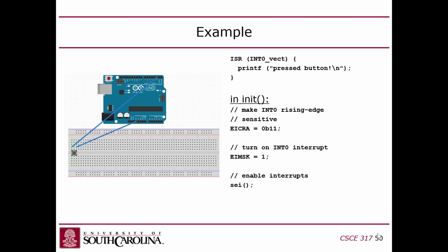All right. I don't show what I have after this, but it could be anything. It could just be an infinite while loop after this. This just sets up the interrupt. Once you've got the code running, whenever you hit the button, it'll print push button. So that's a really simple way to set that up. And obviously, you might say that's kind of trivial. Well, we're going to build on this and use it to build more complex systems.